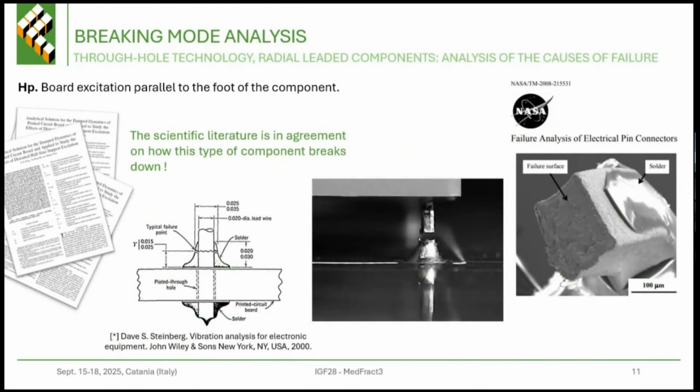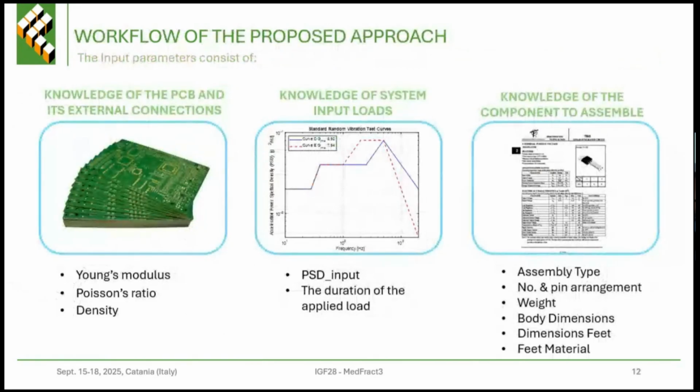Another thing on which all the literature is in agreement is the failure point, which is always in this part, very near to the solder. From Steinberg to the NASA report, all report that the failure is at this point.